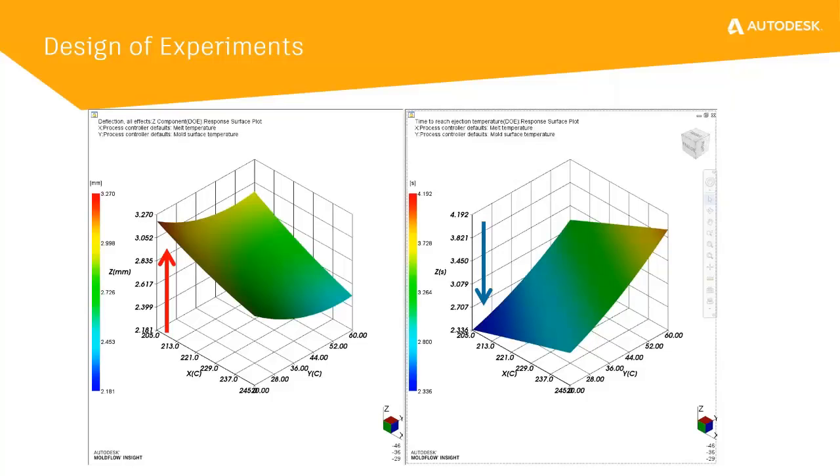The warpage plot also shows that deflection is more sensitive to melt temperature changes than to mold temperature changes, since the slope is steeper for the melt temperature axis. This information can be used by a process engineer before running additional molding trials or capability studies to identify the dominant factors and what variables can influence a specific part response.